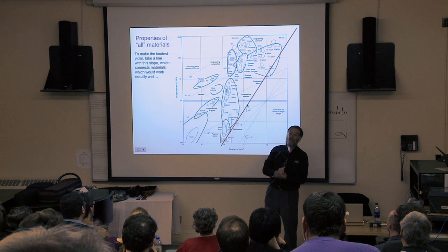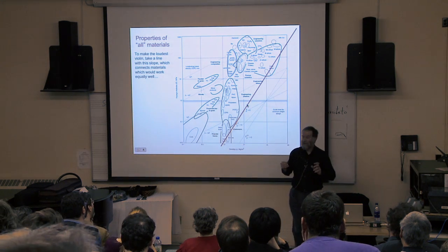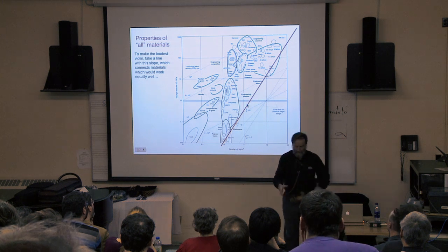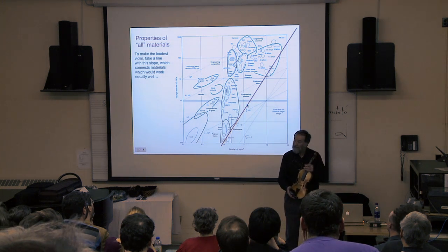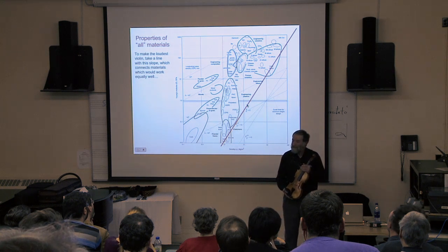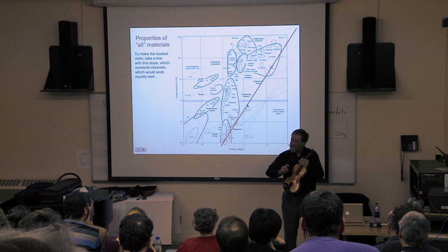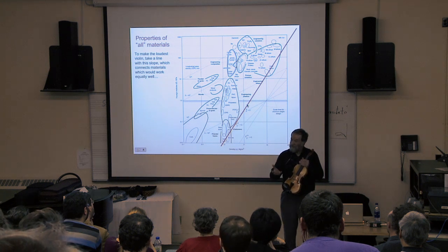What will determine how loud it is? And so we can go through a rather simple design calculation to say we're going to make something, it's going to be this size, it's going to have resonant frequencies that are in the usual place for a violin body. I will adjust the thickness to achieve that. Right? How loud will it be?